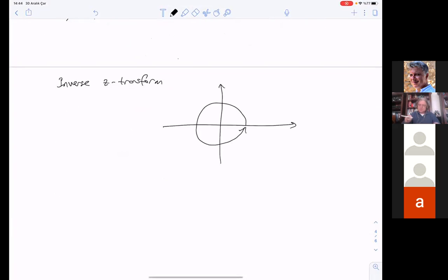Take this integral, okay? It's a contour integral, a complex integral, which is the definition of the inverse Fourier transform. That's a place where you can take the integral, r is equal to 1, which means don't take the inverse Z transform, but take the inverse Fourier transform. But if the unit circle is not included in the region of convergence, you cannot do that. Then you may have to choose another radius r and take this integral instead.